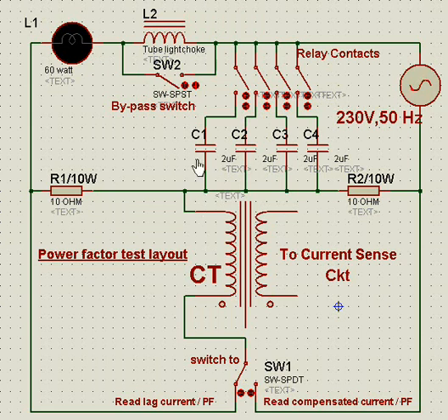And if you want to see the linear load, we bypass the inductor. There is a switch here; we bypass the inductor, so the current flows bypassing the inductor directly to the lamp, and we know the lamp is a linear load and the power factor would show very close to 1. That will be sensed by this and displayed accordingly.